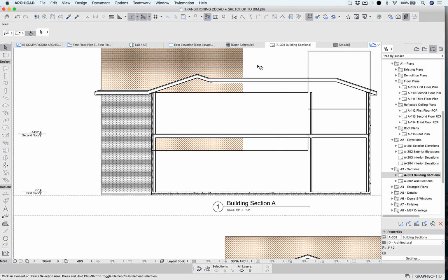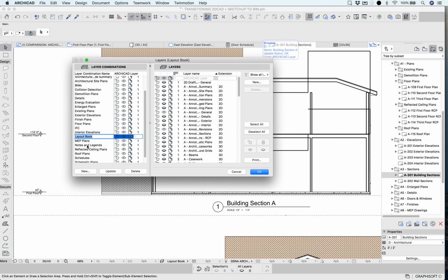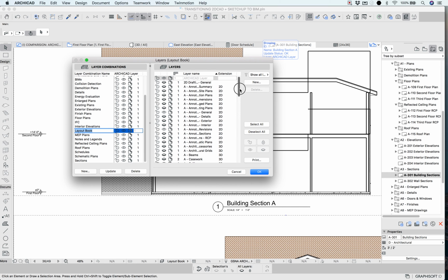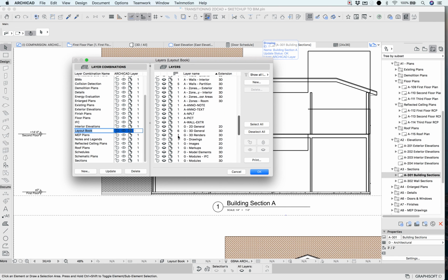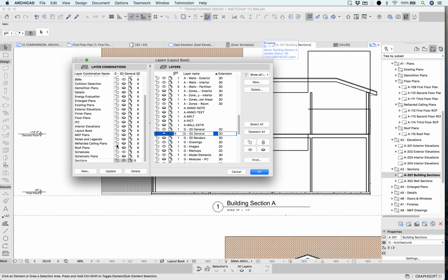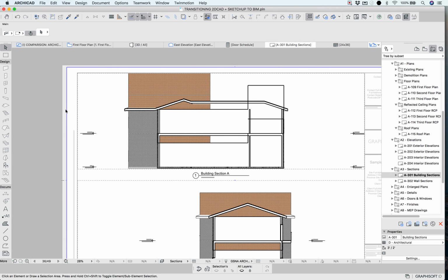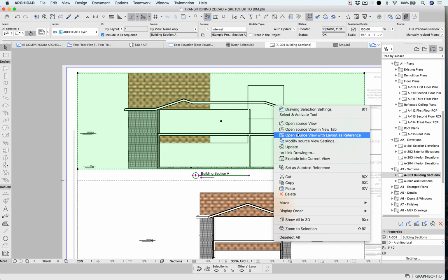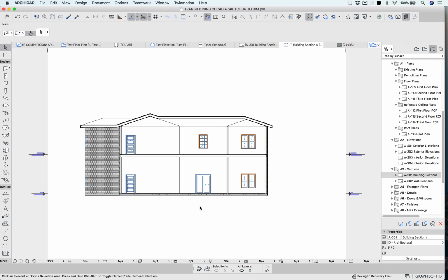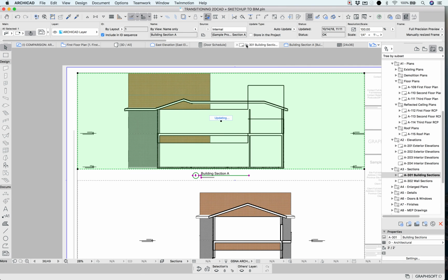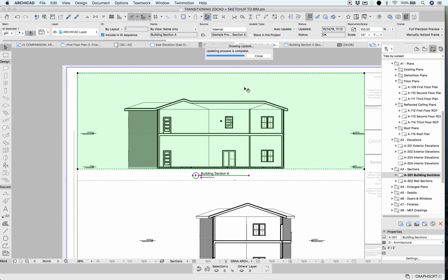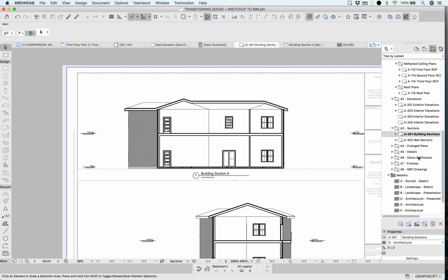Those massing elements. Once again, I could come here even while I'm in this layout book. And I've done this on purpose, just so you know, they don't always automatically have to be on here, but I can update it in one place. Give it a second to update. These are going to be updating everywhere. So you can always go back to my source drawing views, right? So right now we're looking at the source drawing. We could go back into our sheet. It's going to update just to say, okay, that's not the information that's available. This is where we become more and more efficient with BIM.